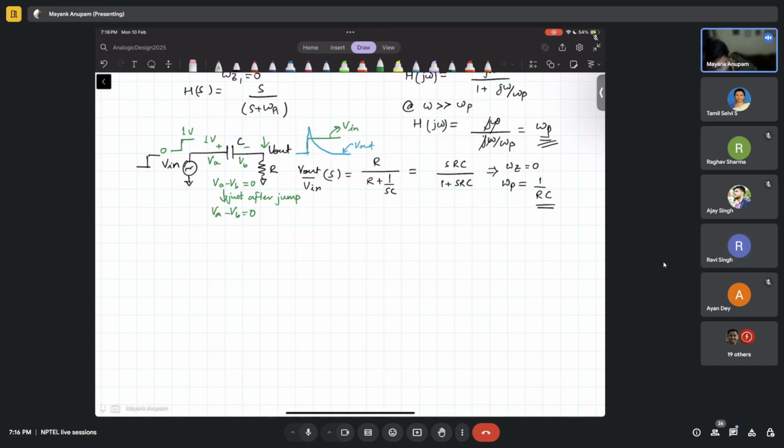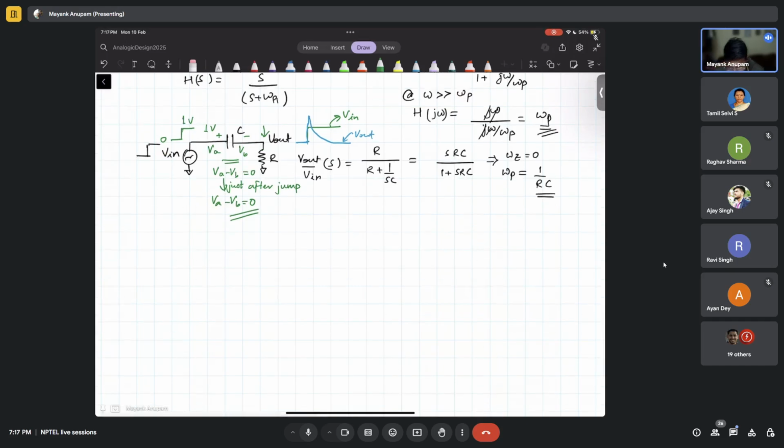First let me ask you whether you understood this or not. That the voltage across the capacitor cannot change instantaneously. Is that correct? Yes, sir. Good. So if the voltage across the capacitor cannot change instantaneously, mind it, I will come to this point, by the way: this is not a sacrosanct fact. It is not always true. I'll come to that later. But at this point, it looks like the voltage across the capacitor will not change instantaneously, right?